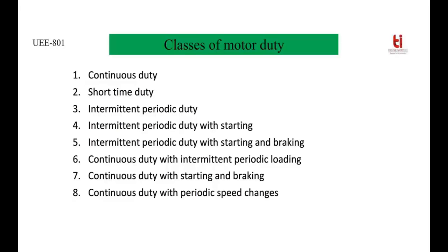Now, intermittent periodic duty with starting. That means some duration it is on, some duration it is off, like this. But during the on period also, initially you can say it is starting. Starting means that during on-load conditions, at the time of starting, the motor will draw a larger amount of current.